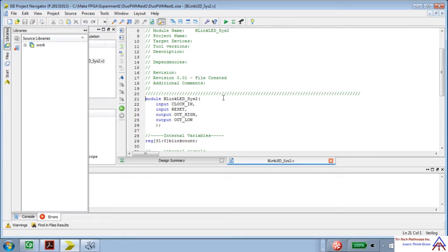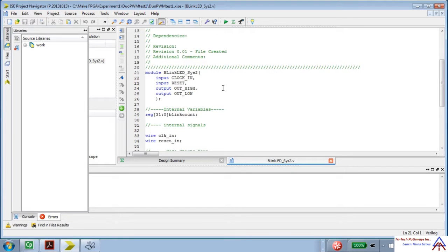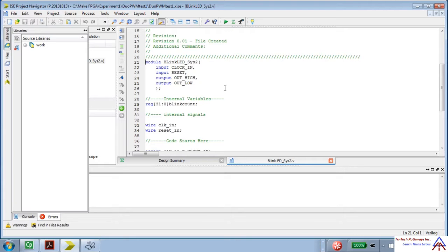So here's the HDL from the GitHub repository. We're going to make a few simple edits of this file just to start with. We're going to use this file to test out our pin mapping. Remember, we're going to take the UCF file that we used in Chapter 2 of the book for the Opal Kelly FPGA board, and we're going to have to remap those signals to the Papilio Duo board.